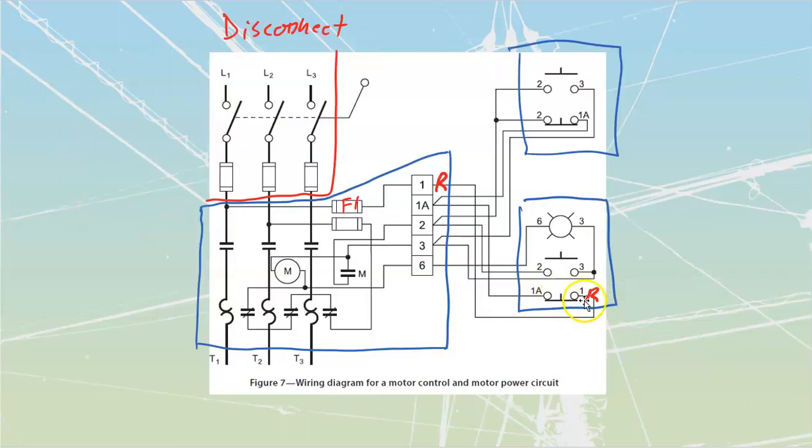That's as far as we've traced it, right? We got the 1 in. We're now leaving. Let's call that the blue that we have for there. I'm going to trace my conduit down until I find where that blue enters. Perfect. I see that the blue comes in. It hits this 1A terminal over here, and then it goes and leaves again.